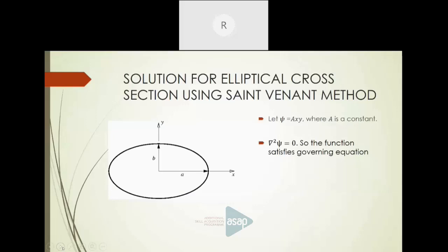Okay, now what you are going to get is G alpha into dou square psi by dou x square plus dou square psi by dou y square is equal to 0. G alpha can be taken to the other side. So what you are having now is del square of psi is equal to 0. Okay, so we got an equation. We can make use of this equation somewhere to solve the torsion problem. We will see that. Now going to Prandtl's method.